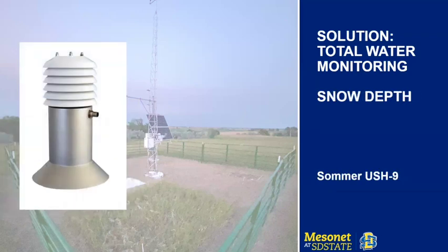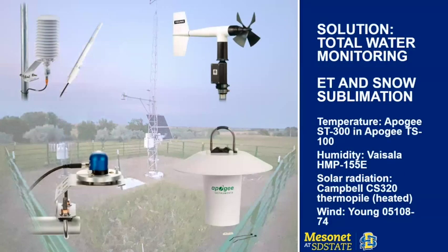Snow depth sensors, because really, if you think of the snowpack, it's precipitation that hasn't fallen all the way yet. So we have to measure it between when it's fallen into the gauge and when it actually melts to go into the soil or sublimates. So we've got temperature corrected sonic snow depth sensors. We also do ET or snow sublimation. The reason I lump these together is you need temperature, RH, wind and solar radiation to do both of those. And so it gets us some extra mileage out of stuff that we traditionally used only during the summertime.